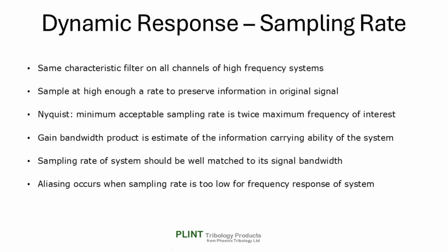As the signal is varying twice per day, from day to night, the absolute minimum sampling rate to avoid aliasing would be 4 equispaced observations per day. In practice, a bit more than 4 samples per day would be a safer option, so a bit more than the Nyquist theory suggests. How often is published friction data supported by any form of meaningful analysis of measuring system bandwidth, filtering, and sampling rate?